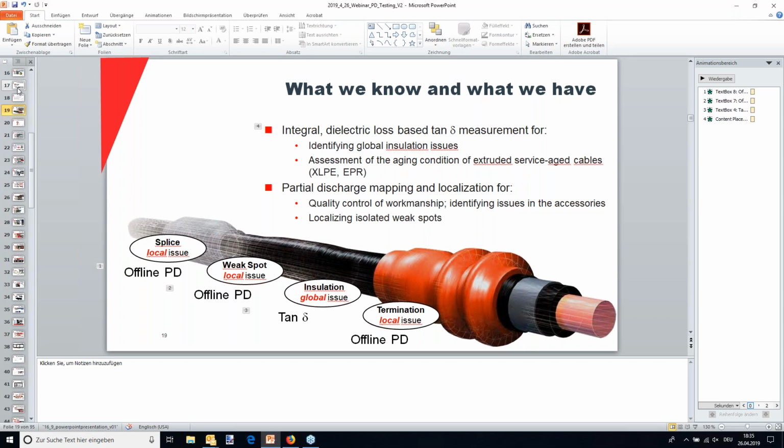But if you have a more problem-prone circuit, you probably say, I'll come back in 6 months or a year and retest, and see if I have degradation. And if something is already critical, PD at operating voltage for instance, or PD above operating voltage and extinction voltage below operating voltage, you might want to come back more often or take action. So that would be a good approach.